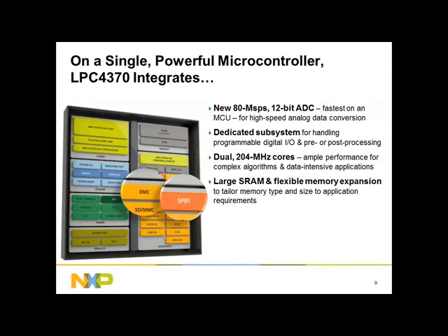Well, the SPI flash interface makes that 4 bits look like a 32-bit bus internally, which means you can execute code from it, you can directly access it. So it's an easy way and an inexpensive way to scale your flash code by dropping in whatever size of quad SPI that you're interested in.